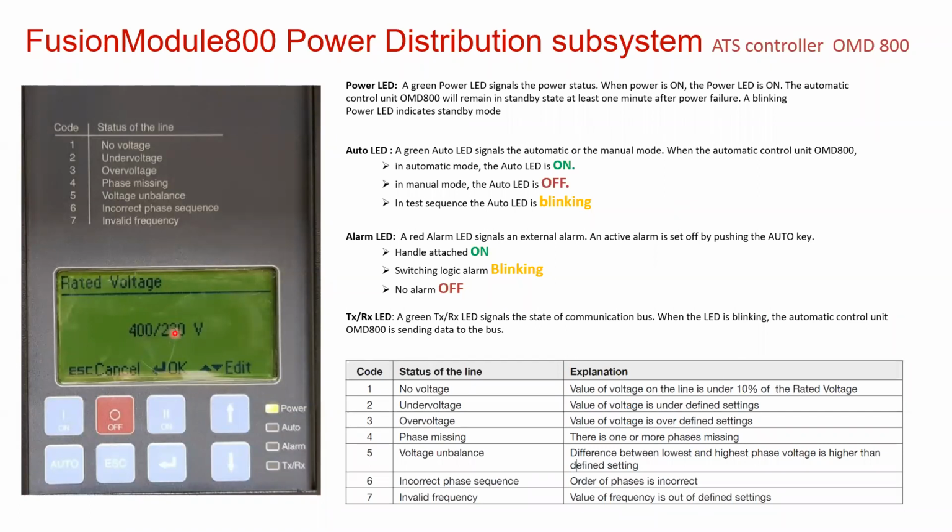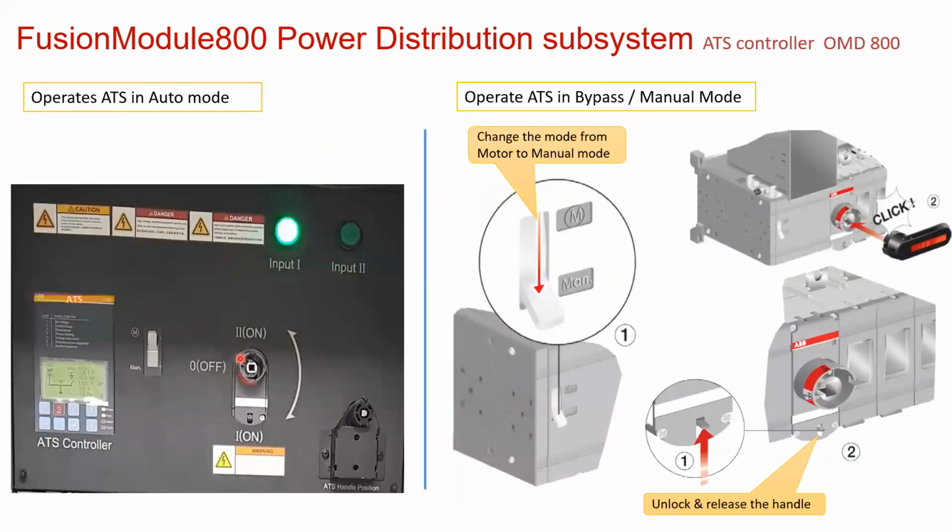The automatic transfer switch can even operate with this fluctuation. It can select another good path, so it can do all these logics and all this monitoring by itself. There is a manual switchover also, in case something happens in automatic transfer and you need to select only one path manually. You can operate this ATS in manual mode and select source one manually. But this operation is only for when your team's understanding is good, that you are choosing manual mode for only source one.